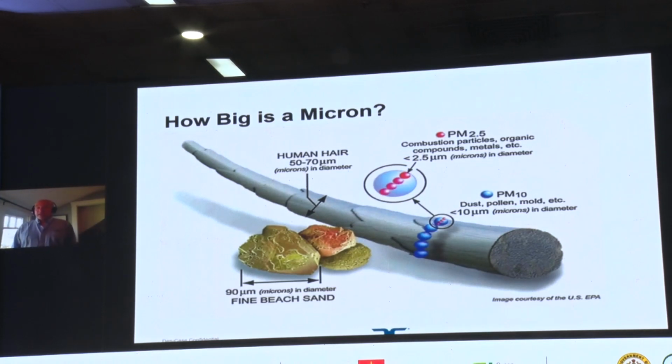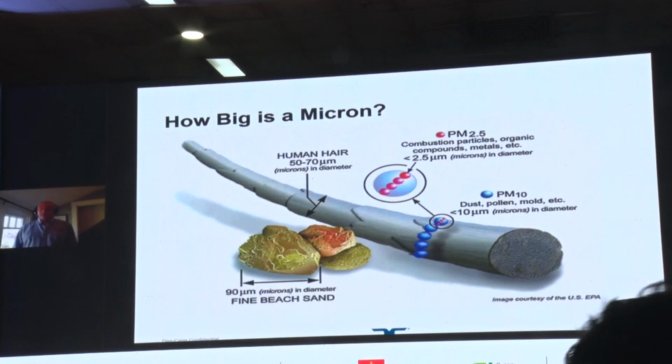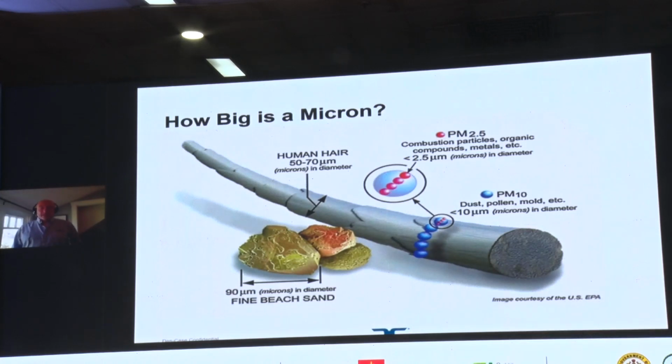So when we think about, for example, an N95 mask, that is designed to keep very, very small virus-sized particles out of the airflow. And that's exactly what we need to achieve in order to optimize the reliability of our gearboxes. So we're going to control or try to control particles in the 1 to 10 micron size range.